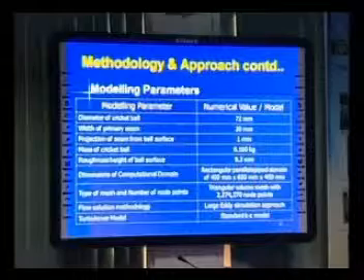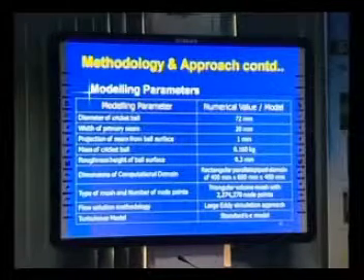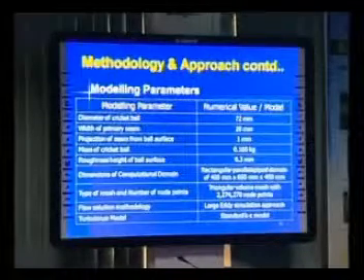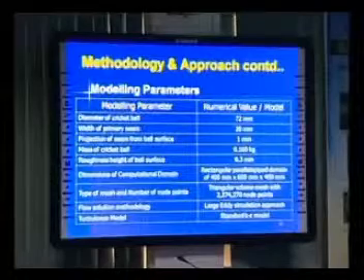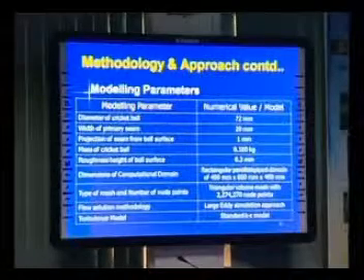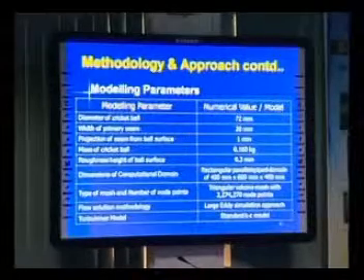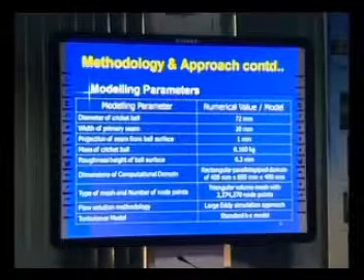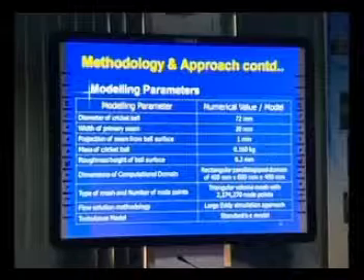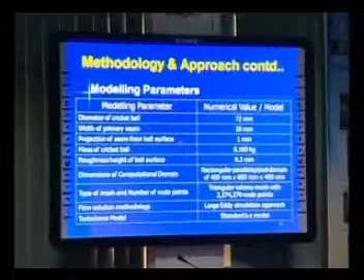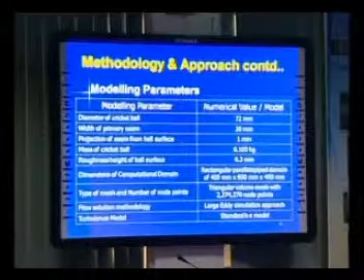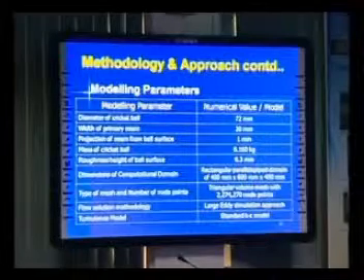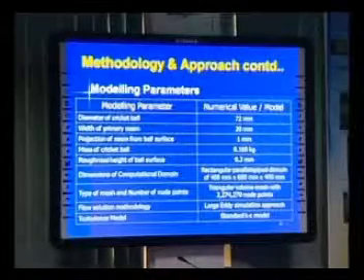These are the modeling parameters that I have used. Diameter of the ball, these have been selected as per rule number 5 introduced by the International Cricket Council, ICC. 72 millimeter diameter, width of the primary seam 20 millimeters, projection of the seam from the ball surface just 1 millimeter, mass of the cricket ball 0.16 kilograms.